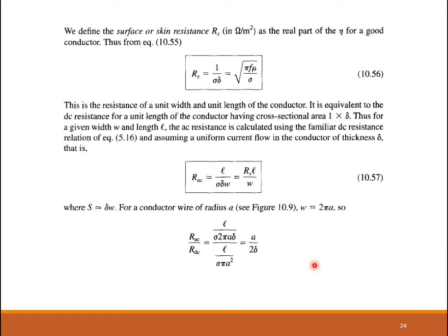Only thing, we need to properly substitute the expressions for alpha, beta, the velocity of propagation, the intrinsic impedance, and the wavelength, and the expressions for E and H need to be correctly obtained. That's all. So for different media, that is the lossy dielectric, lossless dielectric, also called perfect dielectric, free space, and then a good conductor, also called a perfect conductor, for all these different cases, the several constants were defined.